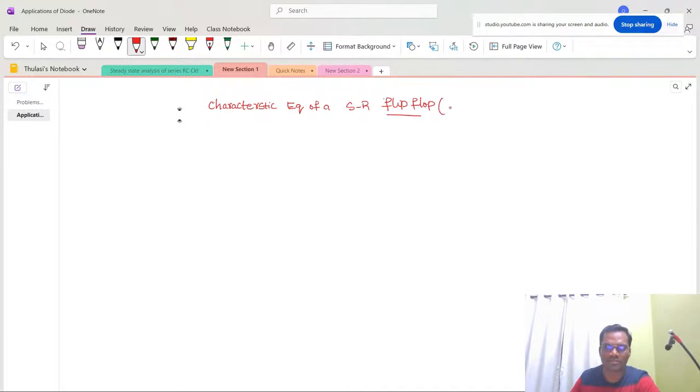This is actually a 1-bit memory storage device, and for the flip-flop to get enabled, it requires an enable signal. So when you give an enable input, it acts like a gate and the flip-flop starts working. Therefore you enable the input with the help of a clock pulse. So the first input we are going to give is the clock pulse, which is nothing but an edge triggered clock pulse.